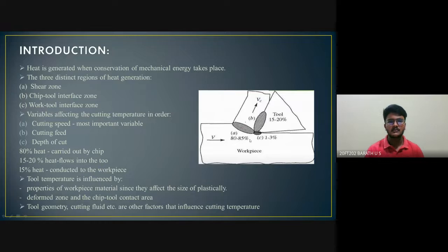In some areas we see blue and dark blue chips formed from the workpiece. Because a high temperature and a lot of heat is produced in that area, oxidation occurs and dark-colored chips are created. This shows that a high temperature was created in that area.